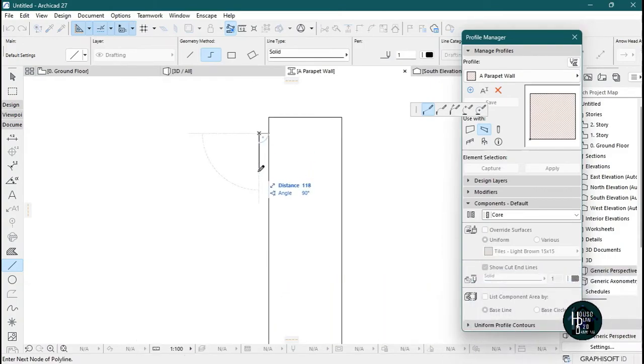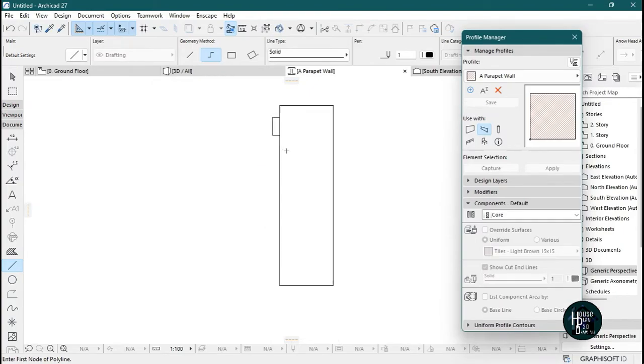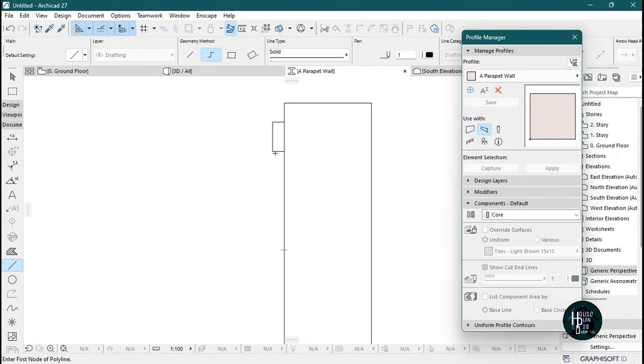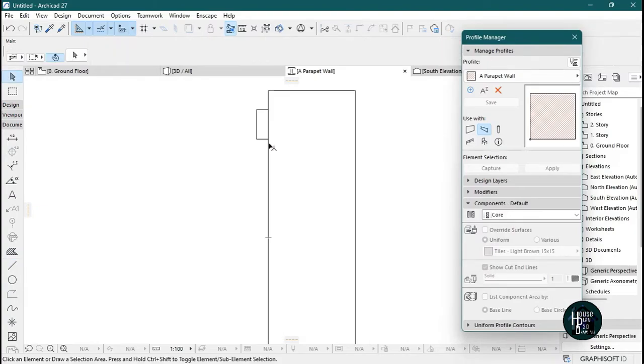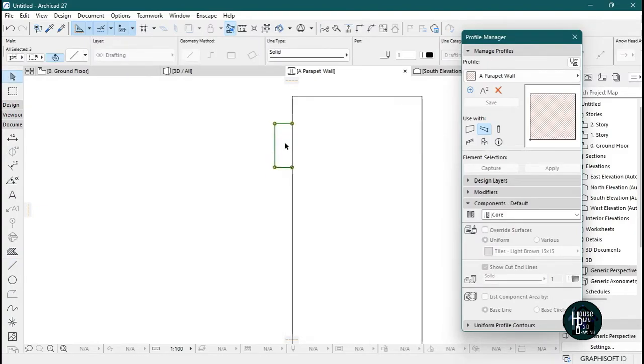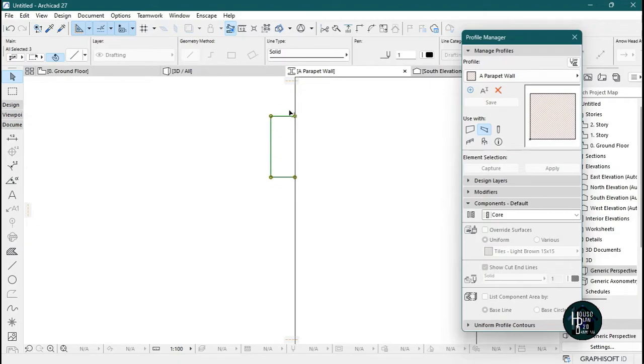Click enter, drag it down and let's give it a distance of, let's say, 75. Click enter and let's take it back by double clicking. Okay, so once you've done that, you might decide that you want to make it longer than this. So if you click on the line to make changes, we can't, because all of this line is being selected.